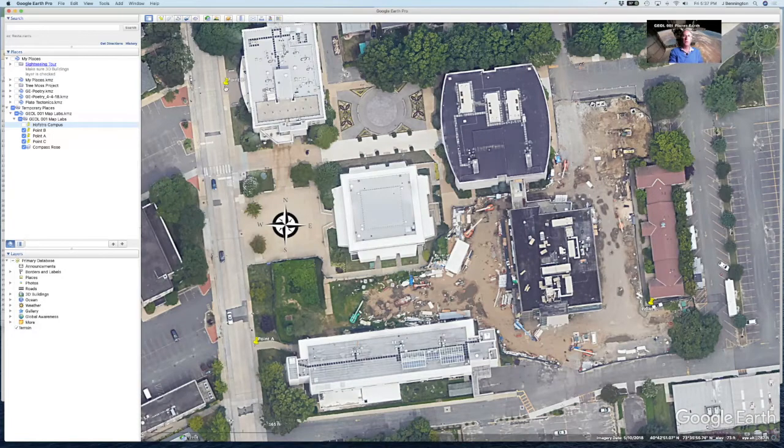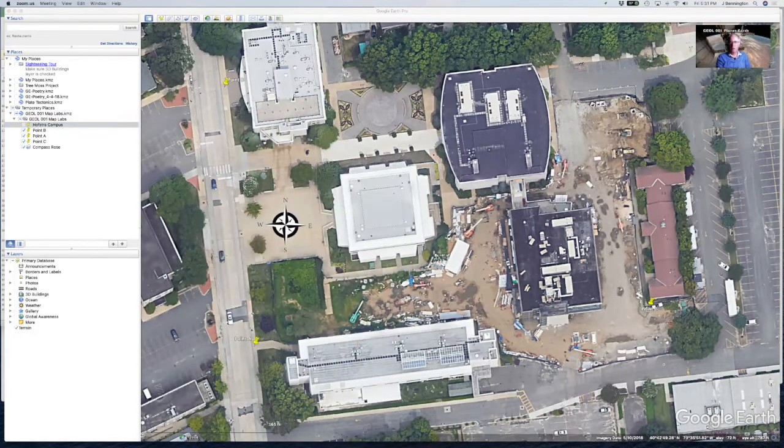of the window. If you move the cursor over the point of one of the push pins, you can read the longitude and latitude coordinates for that particular marked point. You also get the elevation. You can read that, so it will show you the elevation of the location where the cursor is as well. Let's just focus for a moment on the coordinates that are shown in the lower right margin of the map here. I currently have Google Earth set for longitude and latitude, degrees, minutes, and seconds.